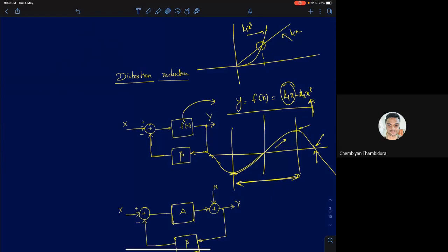So now if you look at this equation, what we see here is that if I inject a signal of frequency cos omega naught t, x is cos omega naught t, because of this term x cube of t, you will also get a term cos of 3 omega naught t. Now this here is distortion. So this term is called nonlinear distortion, distortion arising because of the amplifier's nonlinearities. Now this is what they wanted to suppress or reduce. The first engineers who were building these amplifiers for telephone communications wanted to suppress or reduce this term.